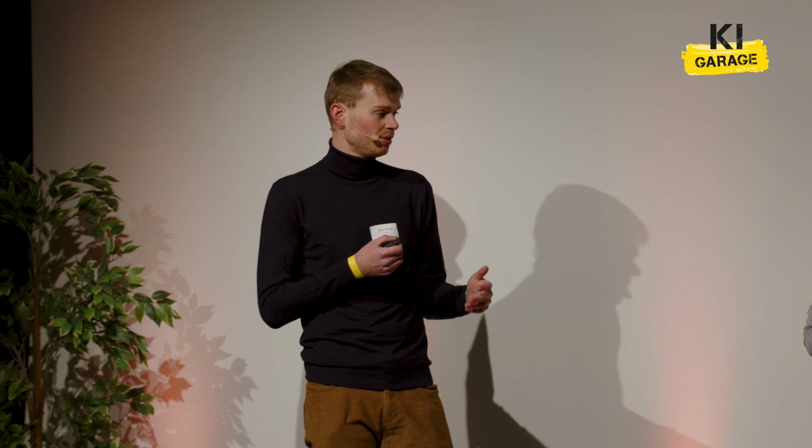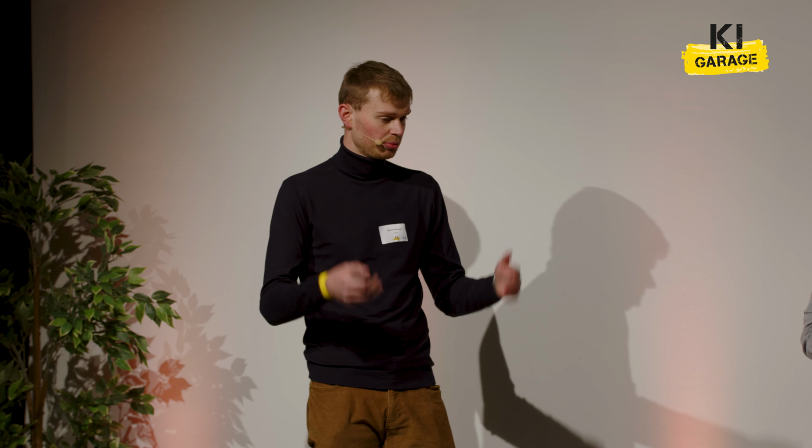There's a physical model behind it, producing simulation data of the different states, so of the fault and of the healthy state. With this, the AI is trained, and then it uses the three phases of the electrical current in the frequency spectrum to analyze the faults. I hope it's clear. Yeah, but I'm sure there are a lot more details.